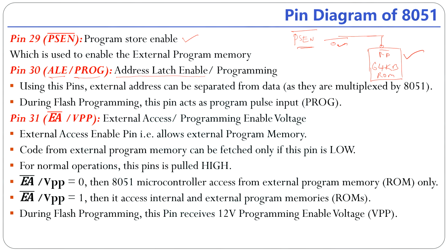ALE stands for address latch enable. PROG stands for programming pulse input. When the 8051 is operating in user mode, this pin is used as ALE. When it is operating in flash programming, this pin is acting as a programming pulse input. First, we will discuss ALE.